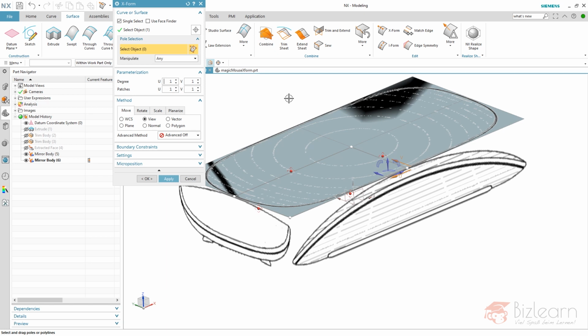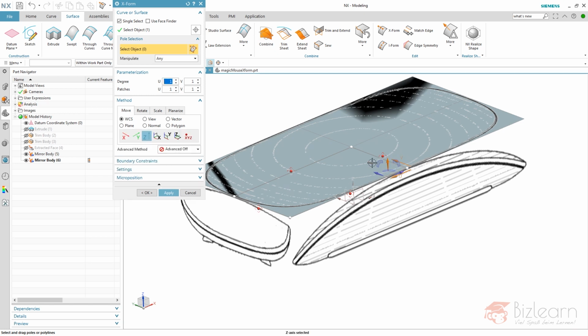Well, normally class A means that we only have one patch on the overall structure of a surface. That's what we won't have, because we're creating one quadrant, which we're going to copy somehow. But we have to do a modification in here. For example, if I move one of these poles, which you see here, I'm just going to move it into Z direction. Just select one of these axes.